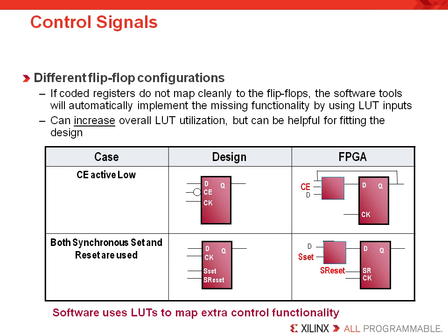Now this is very helpful, but a job only your synthesis tool can do. But if you build with an asynchronous set or reset, then it can't happen. In that case, the asynchronous set or asynchronous reset would be forced to a register control port. Likewise, if you build with an active low control signal, the LUT will be required to invert that control signal by driving it to a LUT input.